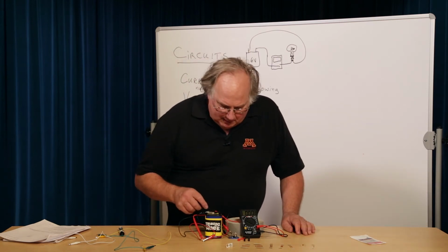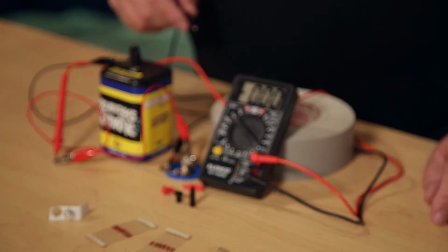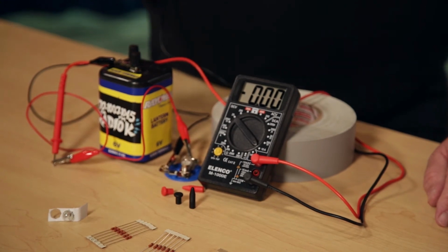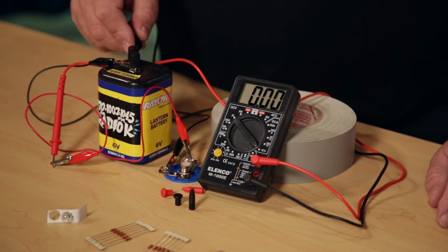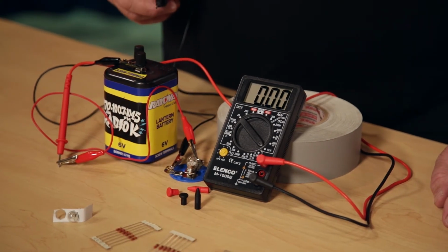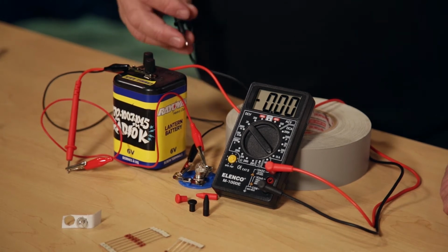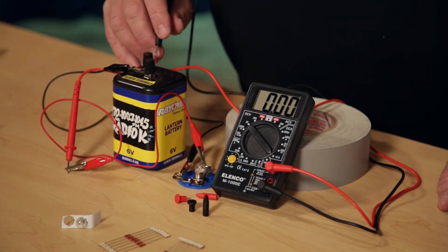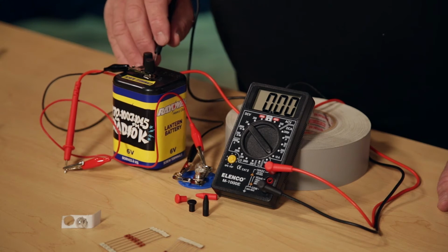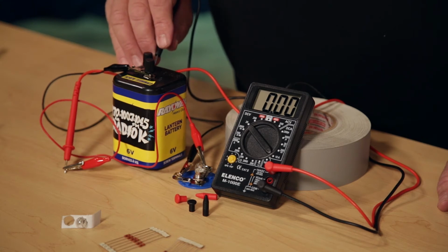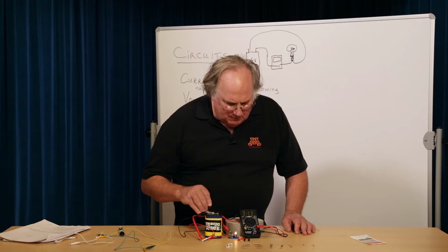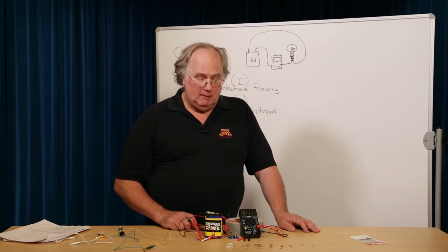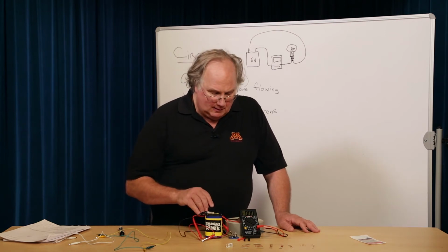Now let's try just a quick contact to see if the bulb still lights up. Bulb lights means the circuit's all connected, all my connections are good. If you don't see the bulb light when you do that, it means one of your connections is no good and you should go through and check things. Now let's try it again, and this time we're going to read the meter, see how many amperes go through there, how much current. And I'm getting 0.32 amperes through my meter. If we try it again, you can see the numbers.